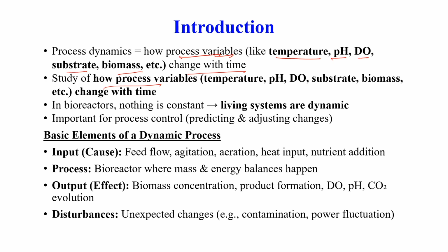Particularly, in a bioreactor we are dealing with a living system, and a living system is dynamic. So all parameters including temperature, pH, dissolved oxygen, even biomass, substrate and product, have a dynamic profile.